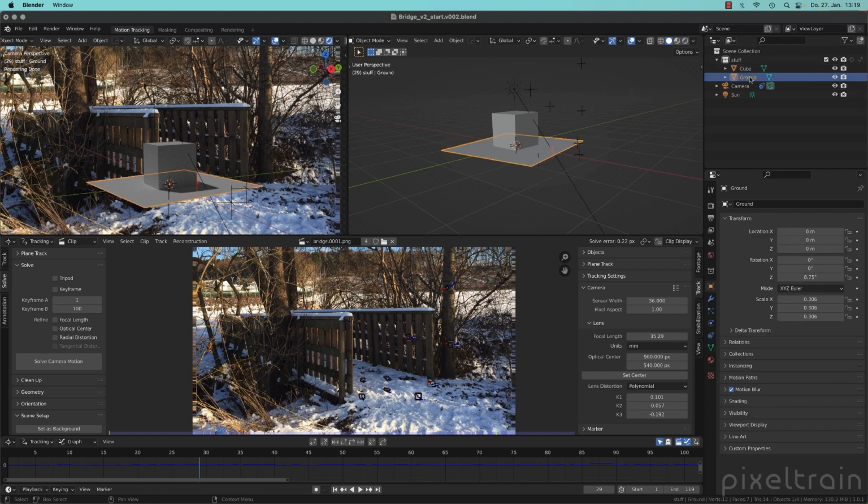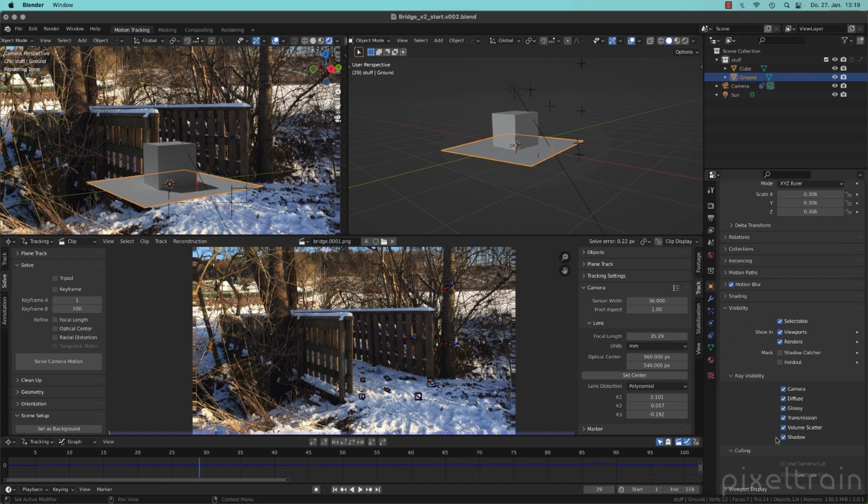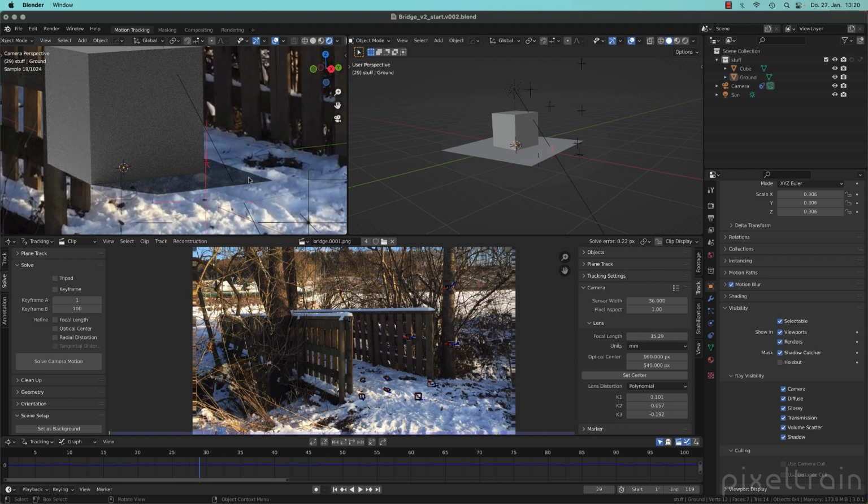So let's select the ground, go into the object settings here, object properties, go into shading, and not in shading, sorry, into visibility. And then you go in here. Don't change the ray visibility. It's absolutely okay like it is. We have to go here to the masking section. And here we tell now the system, I want to use a Shadowcatcher. And in the moment you do that, you will see that only the indirect rays are rendered. Indirect rays are shadows, reflections, and GI, but not the visibility. And now you see here is a really nice shadow inside of the scene.